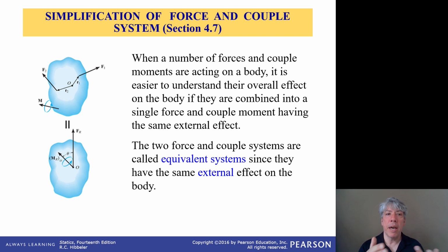And so it doesn't really matter where we choose to apply our equivalent force and moment in terms of the effect on the body, the external effect, the way the body remains in equilibrium. Obviously, it affects the internal stresses in the body. And the nice thing about this is we can choose any point we like and find an equivalent force and moment at that point. Now, that moment will be different depending on what point you take, but the force itself will be the same. You'll see why that is in just a moment.